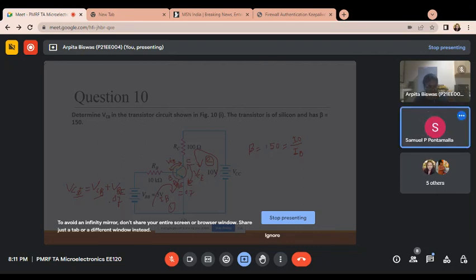43 microamps, madam. Yes, 430 microamps, I think. Just calculate. 43 microamps? Then just see the first equation. Someone just see the first equation. 5 minus IB into 10K minus 0.7, okay, equal to 0. Just calculate in the right way.